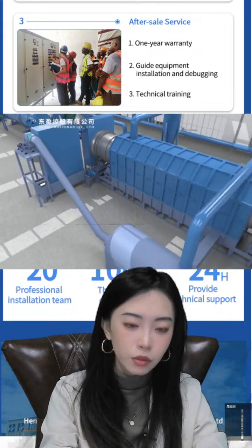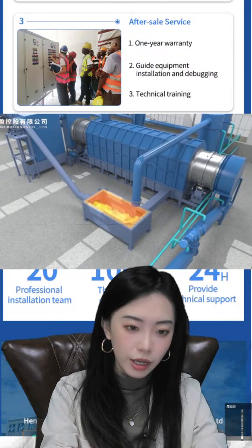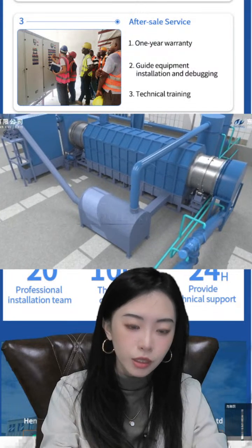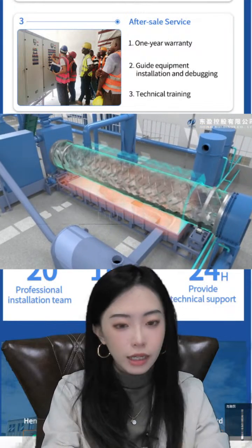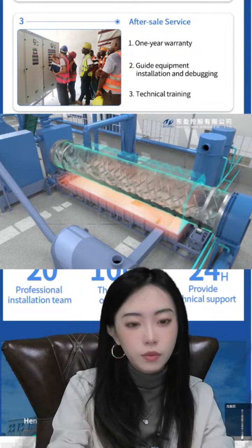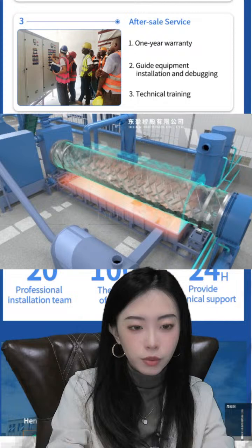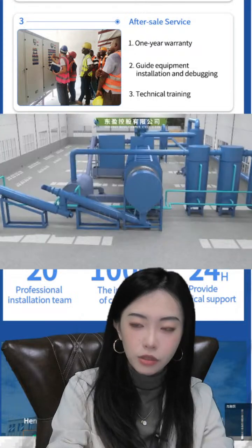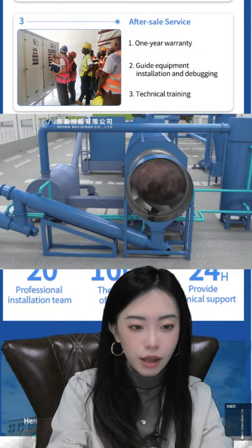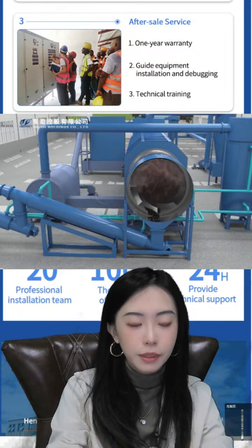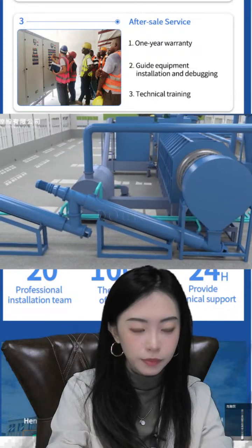For example, if the water content is too high, we will get too much wood vinegar, not charcoal. If there is 10% water contained in it, the tar we will get from 1 ton of biomass is 20 to 40 kilograms, and the wood vinegar may be 40 to 80 kilograms.